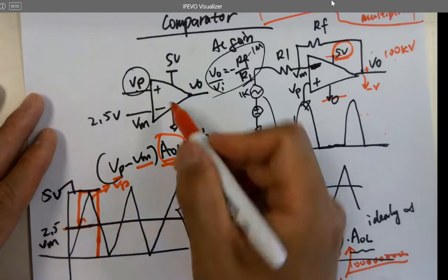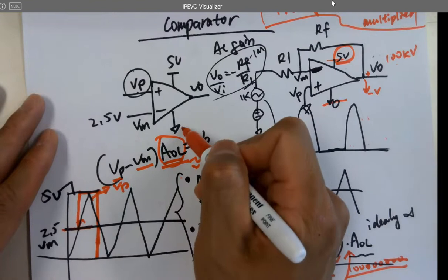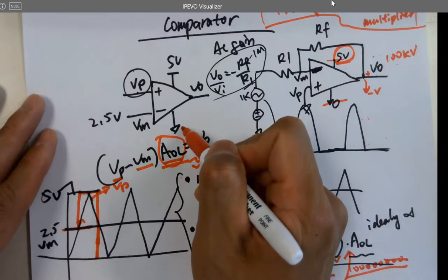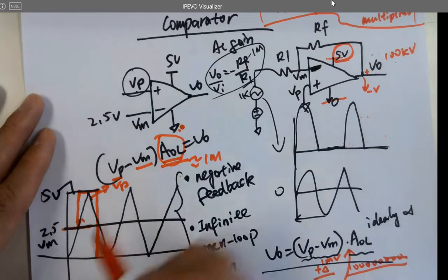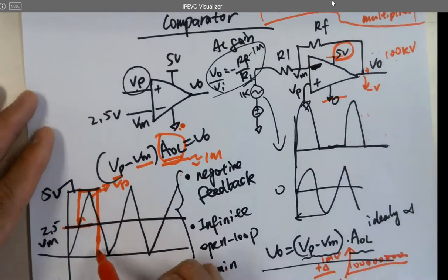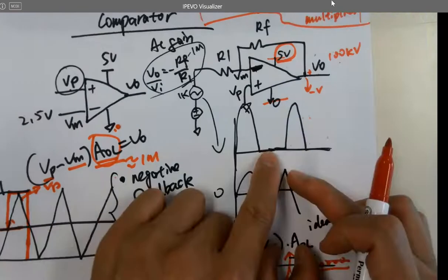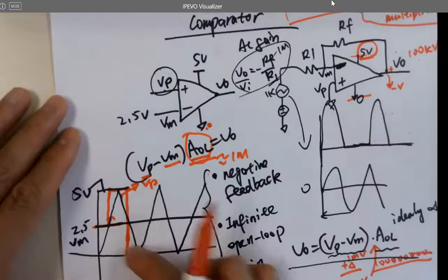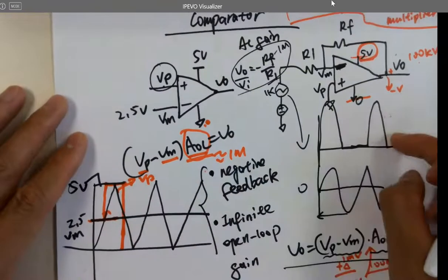To 0, because you don't have negative voltage. This is the lowest voltage you can supply. It's going to saturate at 0 volts. It's actually cutting off the signal, but we intentionally do that. We are using that kind of property here.